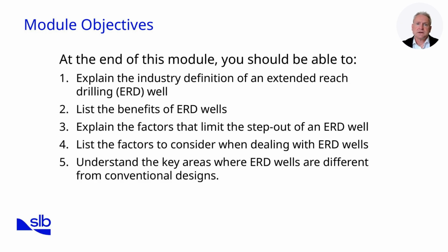Surveying and geological uncertainty is another key theme. In long-reach wells, even small positional errors can lead to missed targets or costly sidetracks. We'll also analyse torque, drag, and buckling, understanding both design forecasts and operational impacts. Finally, we'll explore BHA and drill string design, where hole cleaning capability and tool durability take precedence over rate of penetration. By the end, you'll have a clear view of the design, operational, and risk management factors that underpin successful ERD execution. Next, let's begin with ECD management.